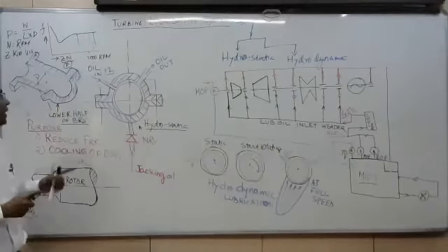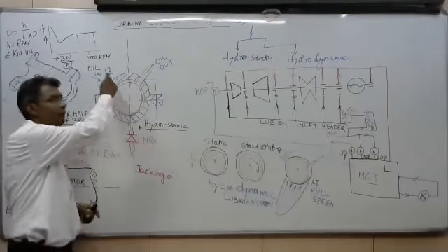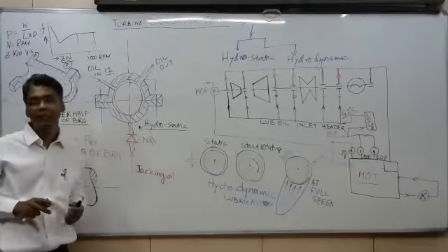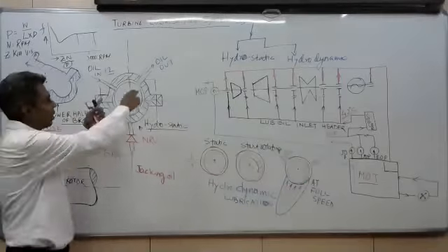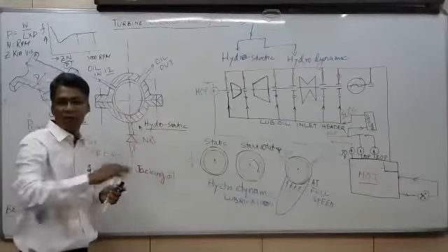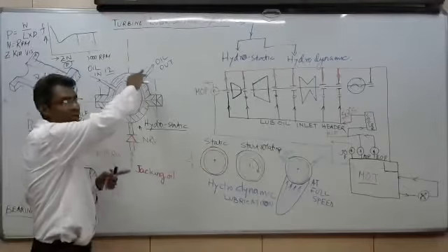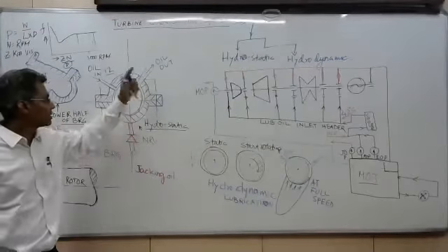The bearing inlet point is always lower than the outlet point, to ensure a certain amount of oil is filled in the bearing. The outlet point should not be below the inlet point, otherwise a certain level of oil cannot be maintained. So the outlet point is somewhat higher and larger in size.